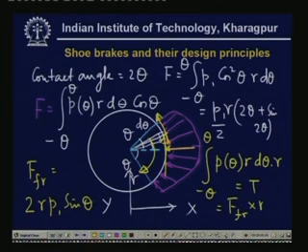Now what we see is that the normal force is F, the total normal force, and the total frictional force is Fr, and of course we have forgotten this important thing, mu. So therefore this is twice mu times r P1 sine theta. We must remember that the total friction force is mu times this force acting over here, dP. This is the friction, this is the total force on this area, and the frictional force is mu times that.